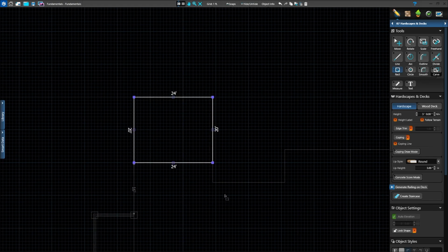Okay, so the front of the house is, we've got our driveway. When we apply the slope, that terrain is going to slope down towards the street or the sidewalk, down and away from the house. In your panel menu, you're going to see the height of your hardscape. We want it set to 0. That's really important because it's defaulting to the kitchen island setting. So make sure you change that to 0.